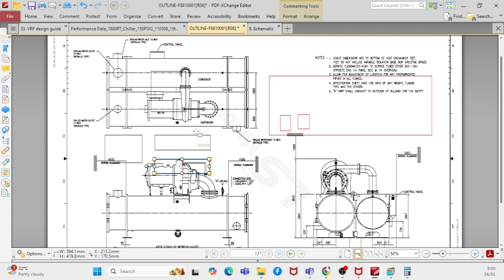But for example, you said the ambient temperature matters only in the scenario where the chiller is outside the building, right? No, but that is for air cooled chiller only. Even for water cooled chillers, you don't require to consider ambient. You don't consider components such as altitude or elevation and ambient temperature as well. Yes.